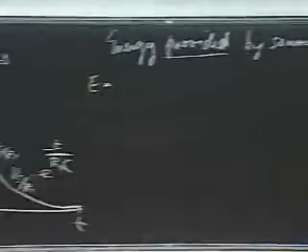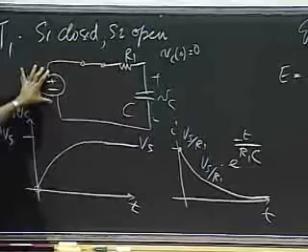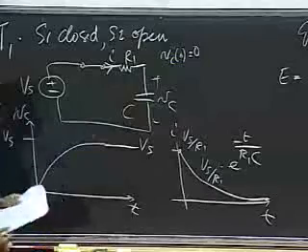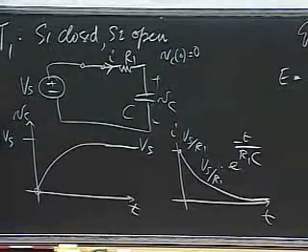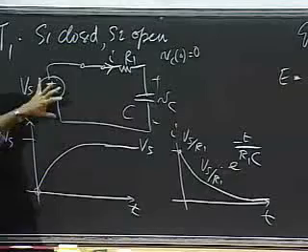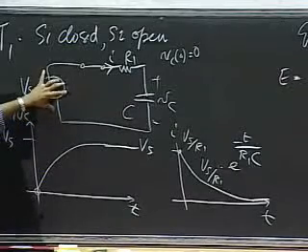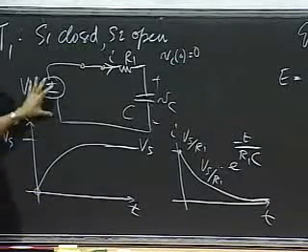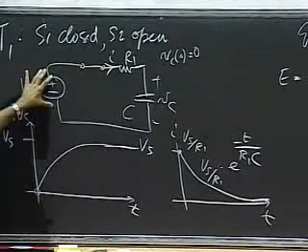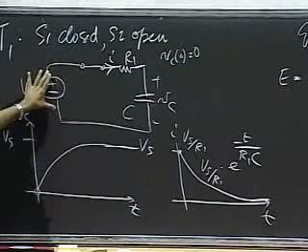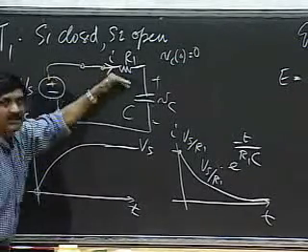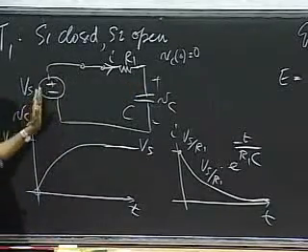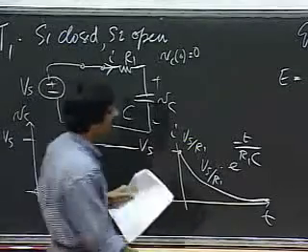So the energy supplied by the source is simply the voltage across the source multiplied by the current being supplied by the source. This is I. Remember, by associated variables convention, if I have a voltage across some element and the current into the element is positive, then that element dissipates power. If the voltage here is, say, 1 volt and it's supplying current, if the I is out in the other direction, then it is supplying power. So in this case, the current I is going to be heading outside.